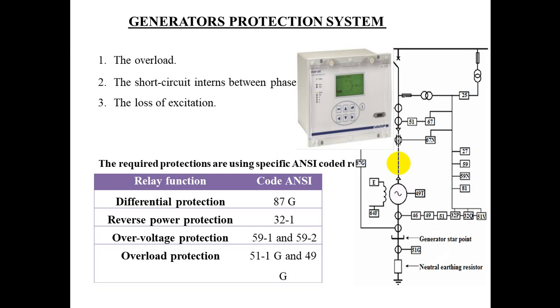Protections against lubrication oil failure. This protection is not considered essential since the lubrication oil is normally obtained from the same pump as governor oil, and a failure of governor oil will automatically make the stop valve close.